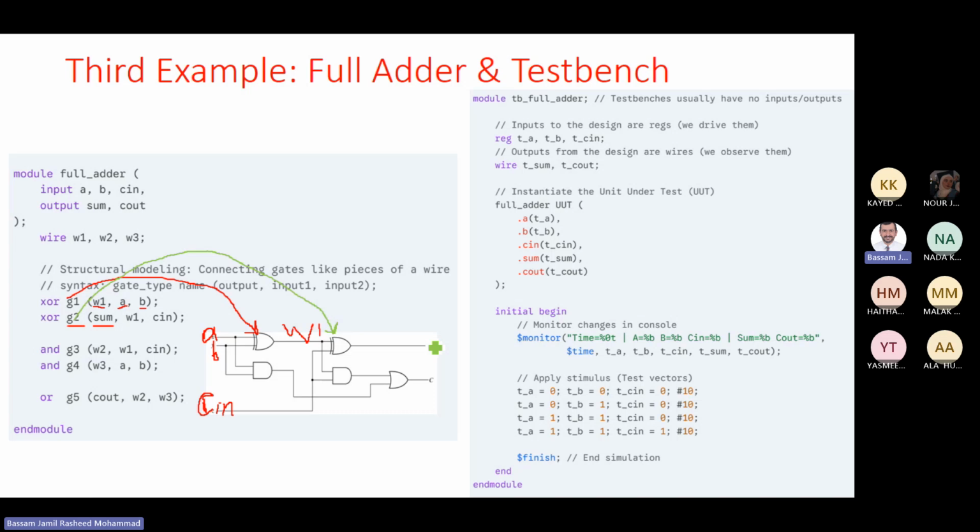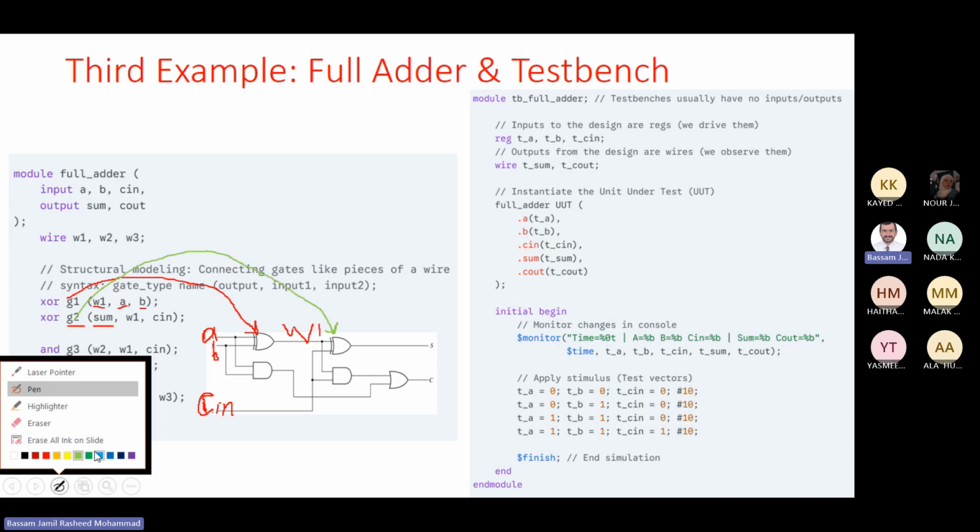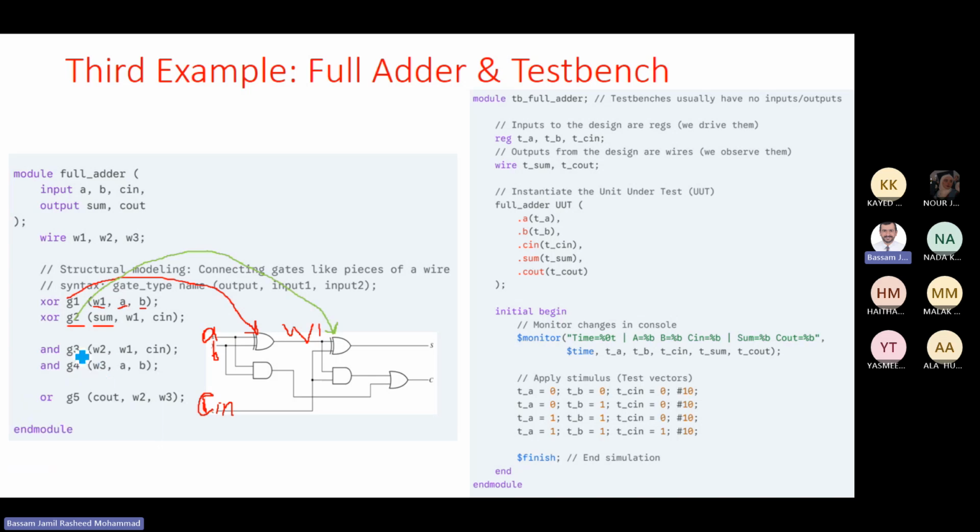Okay, all right, good. Notice the module name, the instance name. The module name is the gate, XOR, instance name, inputs, output. But then what? Then I have this gate here. Let me change color here. Maybe probably do a blue here. Okay, and what do we name this here? This is W3. Okay, and this one is this gate right here.